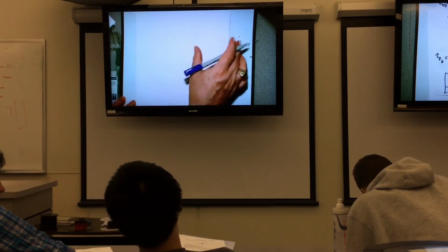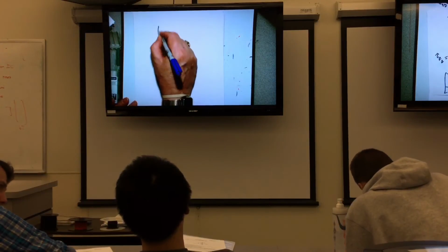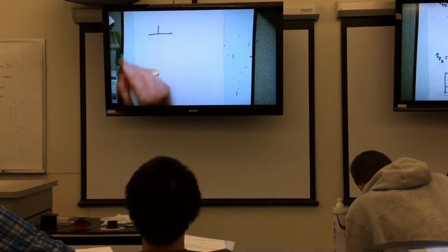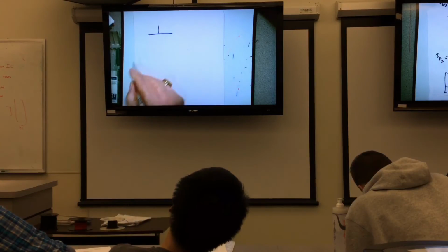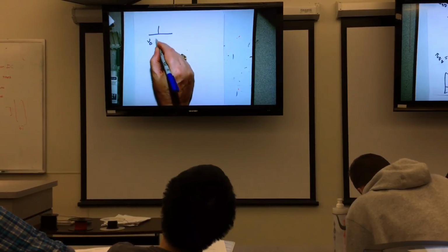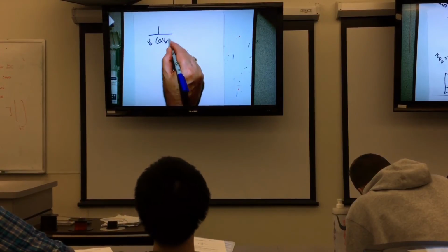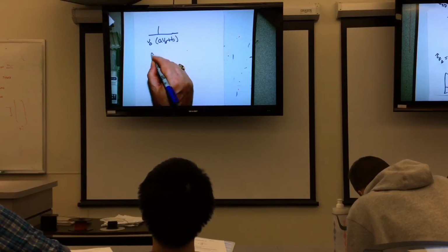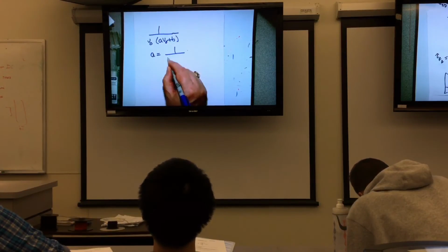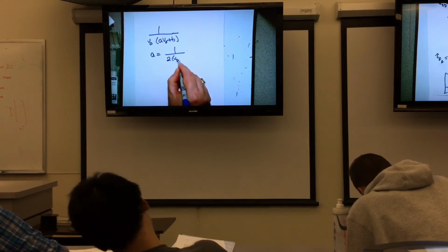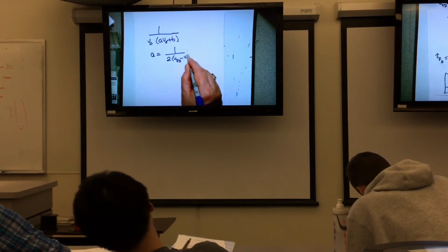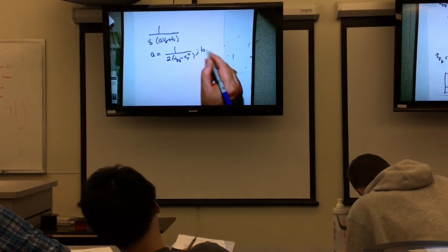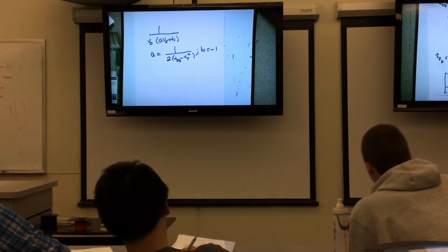And we've got a term in here which is 1 over, effectively, once I factor it out, V naught times (A V naught plus B), where the A is 1 over 2 (VDD minus V threshold N), and the B is minus 1.